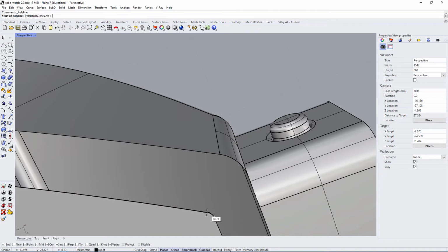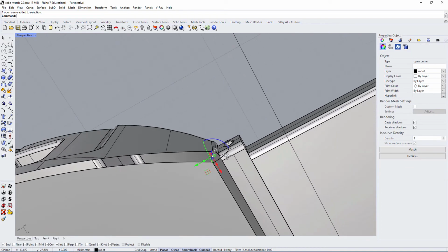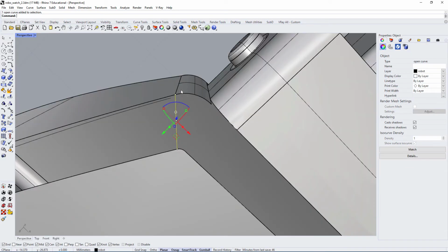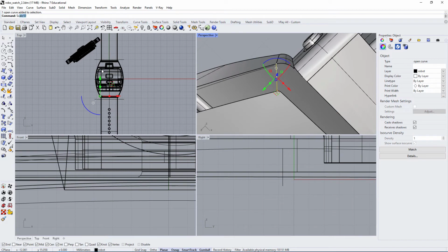And typically, if you trimmed your surface correctly, you should be able to find some kind of edge, like this one. You can take this line here, which gives me the orientation, so basically the relationship between this fillet and this surface, and you can scale that line. You can scale it in 3 dimensions. So in 3D scale, using the center point, you can enlarge the curve.